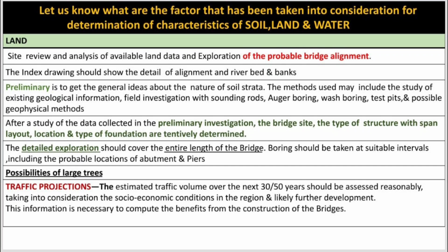For the land, we should freeze the probable alignment, details of the alignment, preliminary investigation, the bridge site, the type of structure, span, etc. Possibility of larger trees. The most important is the traffic projection.